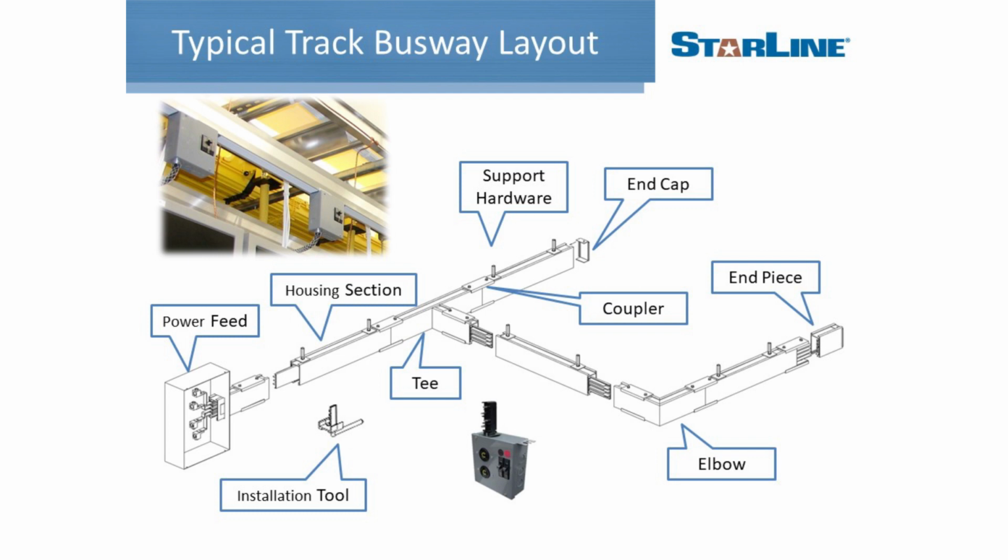So, all things for consideration here, and like I said, we definitely see this as an emerging trend. Typical busway layout system. So once again, you have the power feed where you're incorporating the feed from the upstream PDU unit. We have housing sections and all the necessary piece parts to deal with any potential obstructions or layout that your facility may need. With T-sections and elbows and different things, it's been also easily implemented in scenarios where you're using containment or other cooling strategies where there may be infrastructure overhead that you have to either get around or work through.